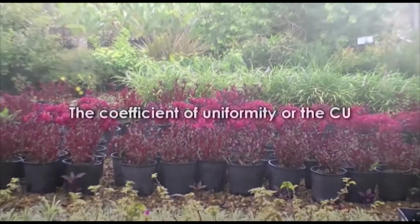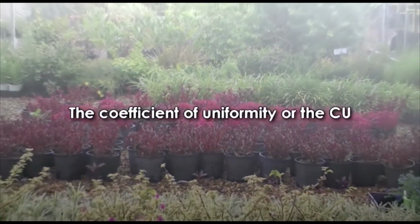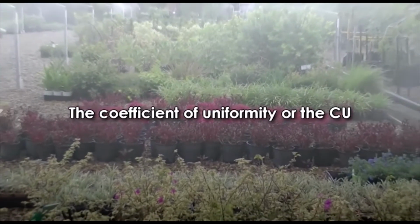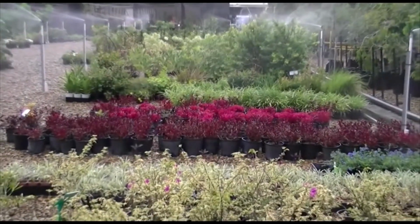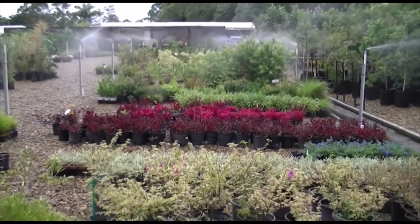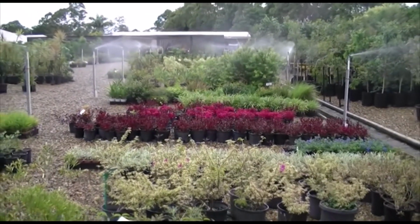Secondly, an irrigation system should apply water evenly across the crop. The coefficient of uniformity, or CU, measures how evenly water application is distributed over the irrigated area. The CU takes both wet and dry areas into account and relates these to the average application.